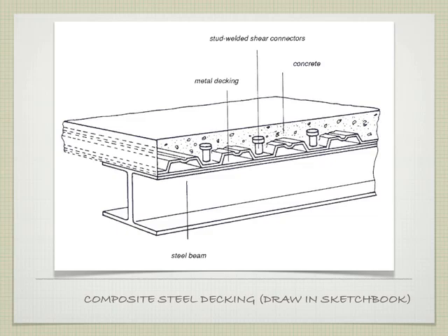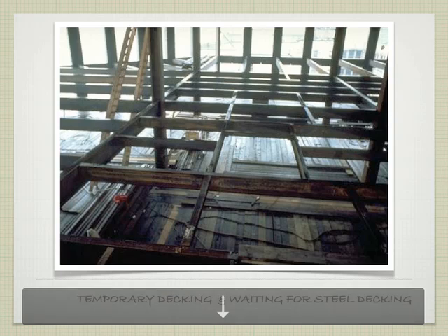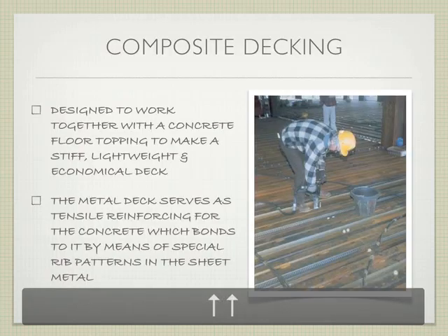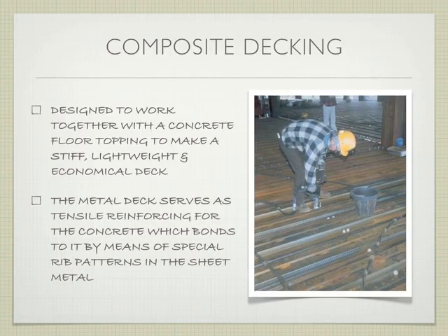Right, so if we jump back a slide, oops, that would be forward a slide. If we jump back a slide, and we're looking right here, this guy is installing those shear studs. So there's one of the shear studs. He's going to put another one in right next to it, and there's a variety of lines for where he's going to put those studs. There's also a whole row of studs here. There's a whole row that goes back there. So this is roughly tying in with wherever the beams are underneath. And that's going to tie that whole topping layer together.